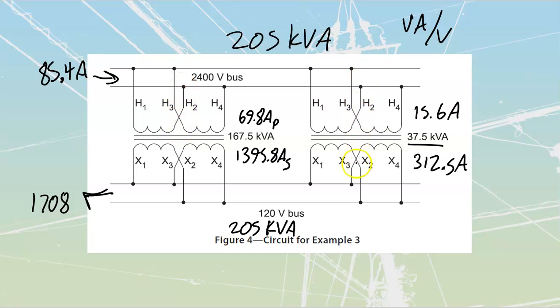Okay, so if I now take a look at my individual windings, each of my windings is going to have to be half of what my overall transformer itself is able to put out, right? This would make sense, that we would have these things equally sized. So I'm going to take a look at my individual windings right now. We're going to develop what current we have inside of each of them. These ones are going to be smaller values.